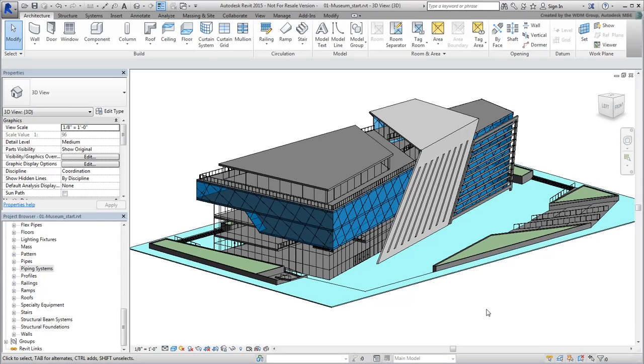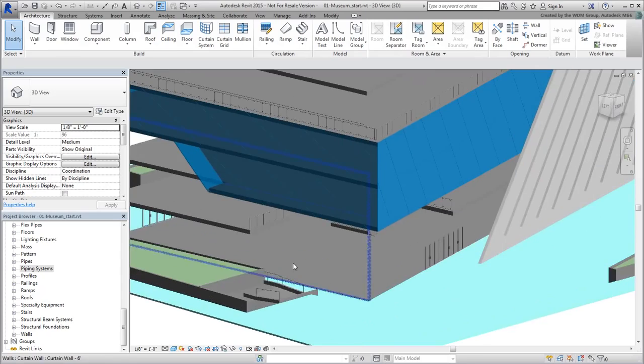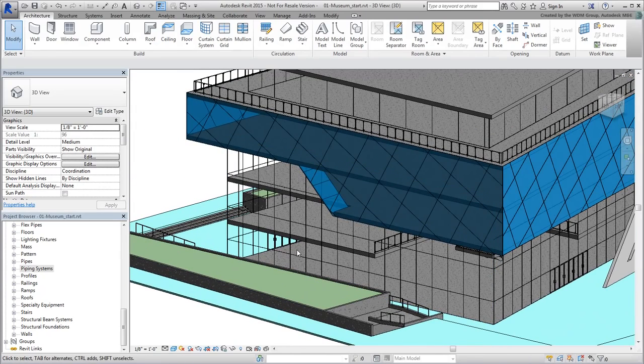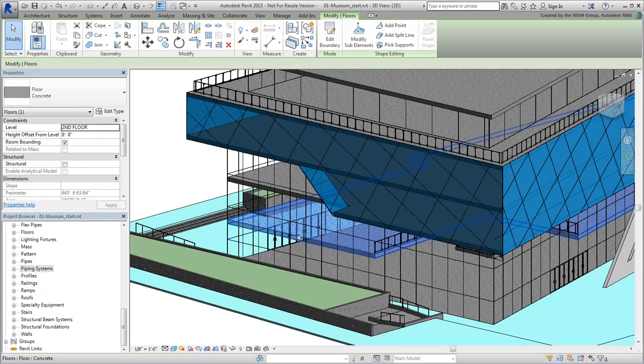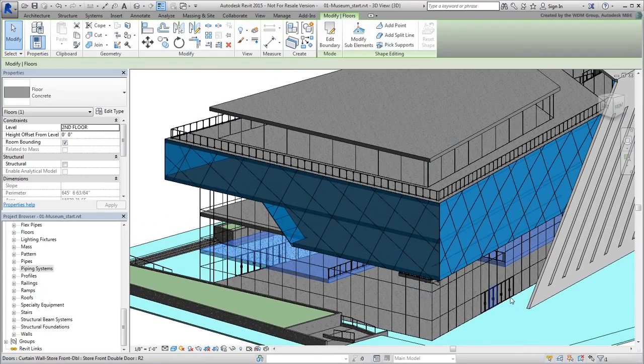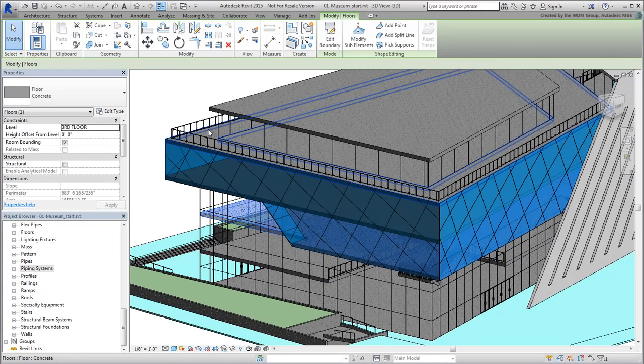Next, let's take a moment to study the floors of this building. Currently, they're all of the same type, concrete floors with a concrete material applied to all sides. Let's say in this example we want the bottom and the sides to be in concrete, but the tops to be on a different material. Perhaps a nice stylable pattern would be adequate. On the other hand, you would want this to apply to some but not all the floors. The roof, for example, needs to have a concrete finish.